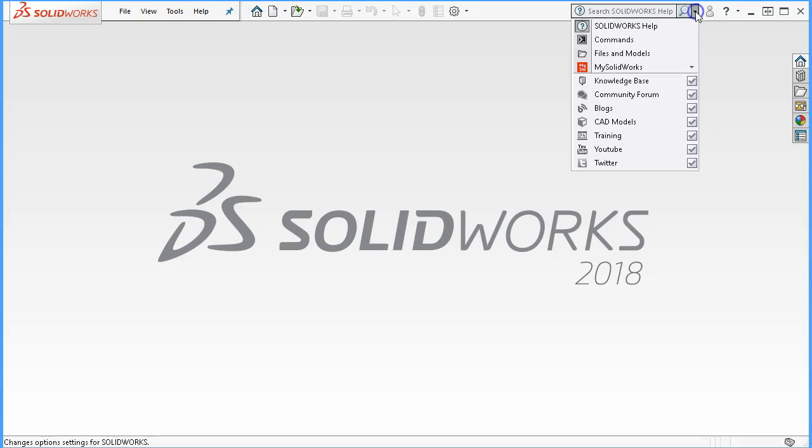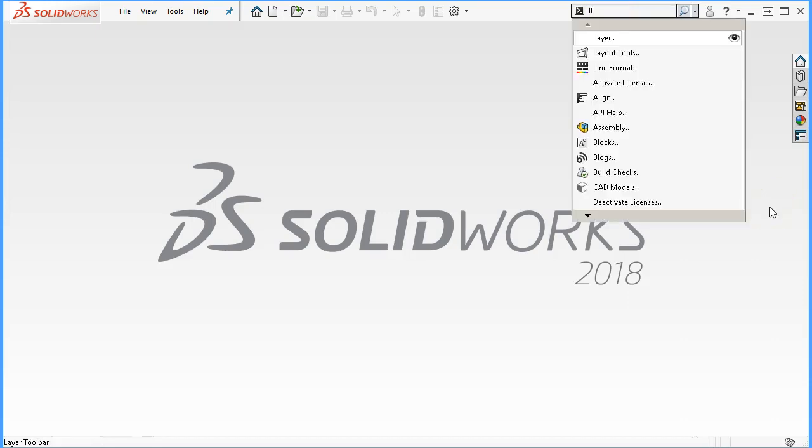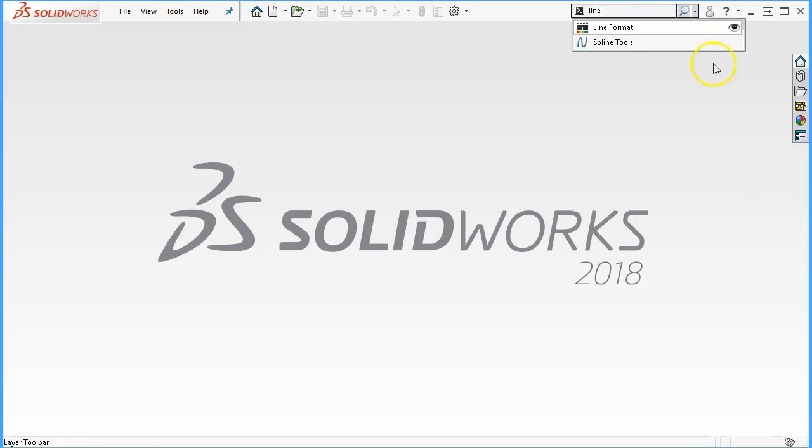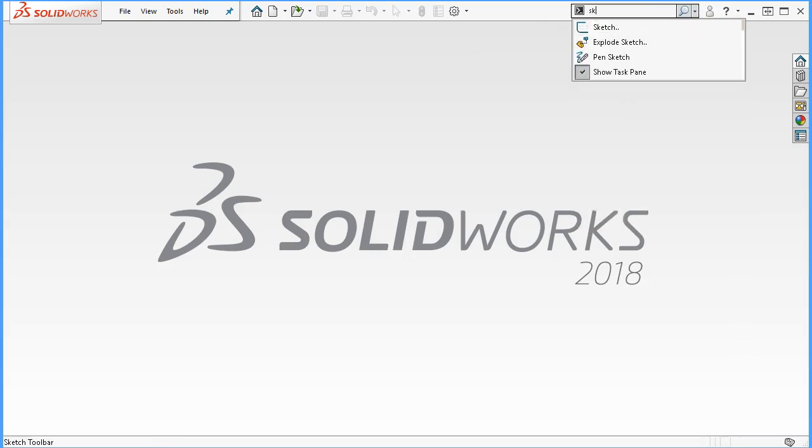On the search, then I'm going to go to commands, and what commands will do is if I start to type in line, well, it went to line format and spline tools, not exactly what I was expecting, maybe sketch. All right, so sketch tools, it will take me to the sketch toolbar or into a command that I'm looking for and can't find on the command manager, which we will get to, or in the pull downs.